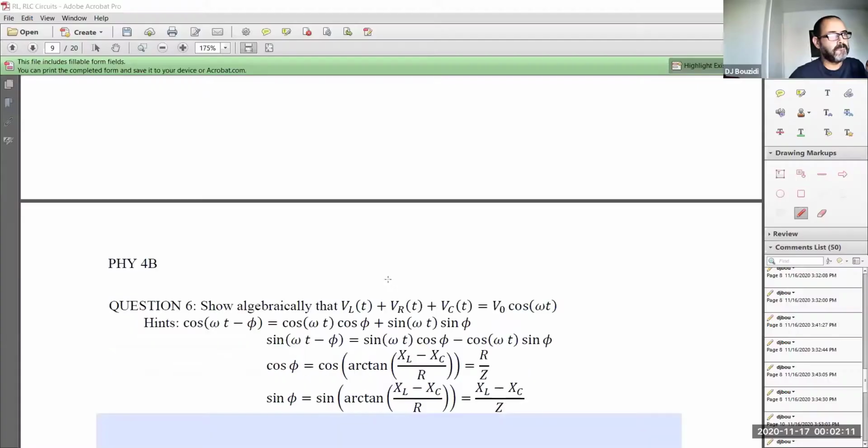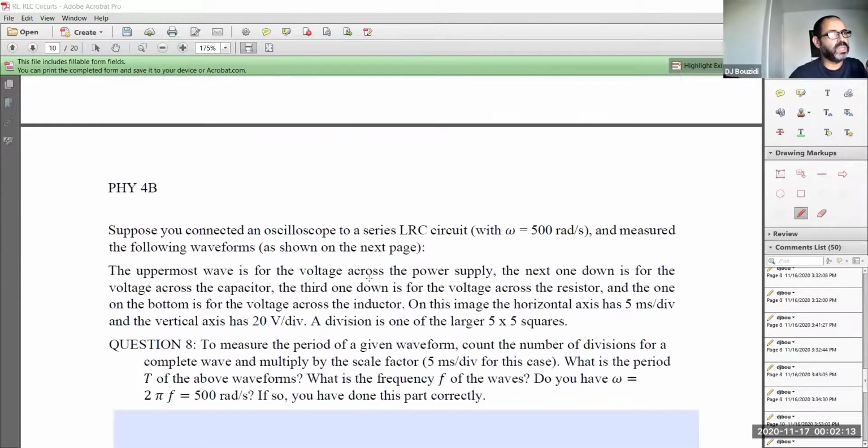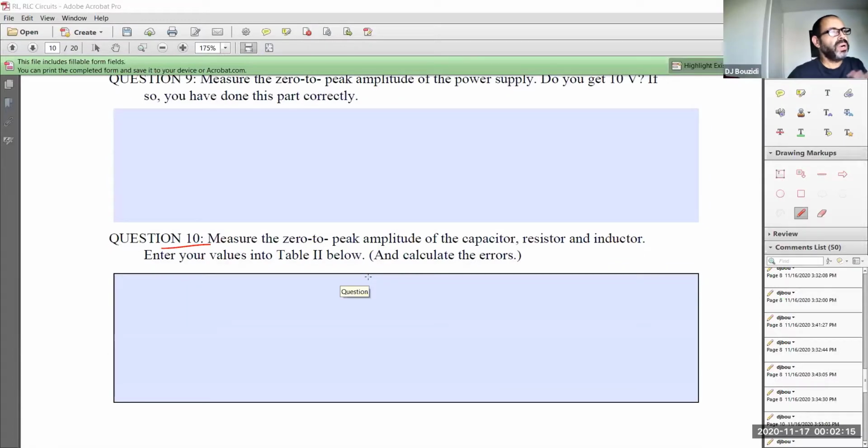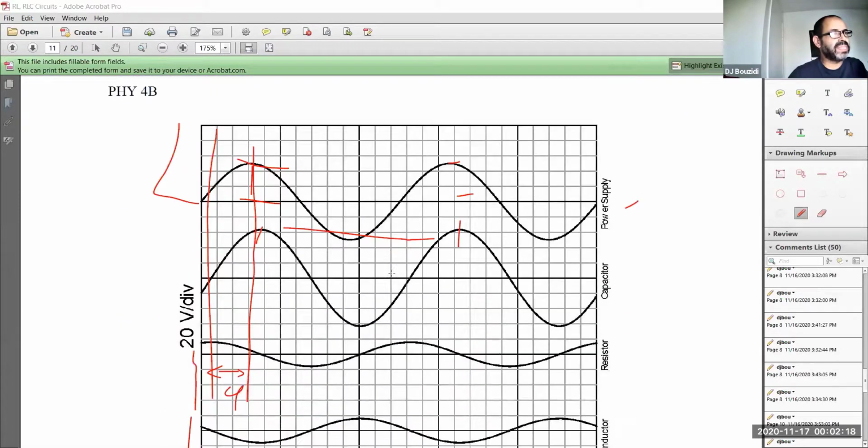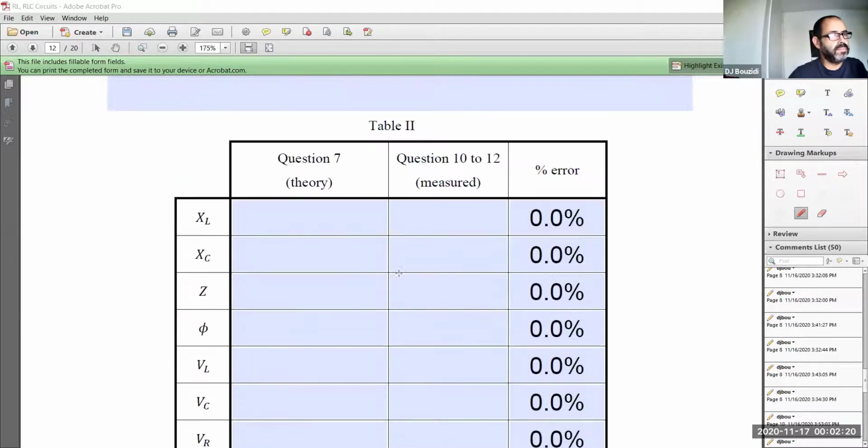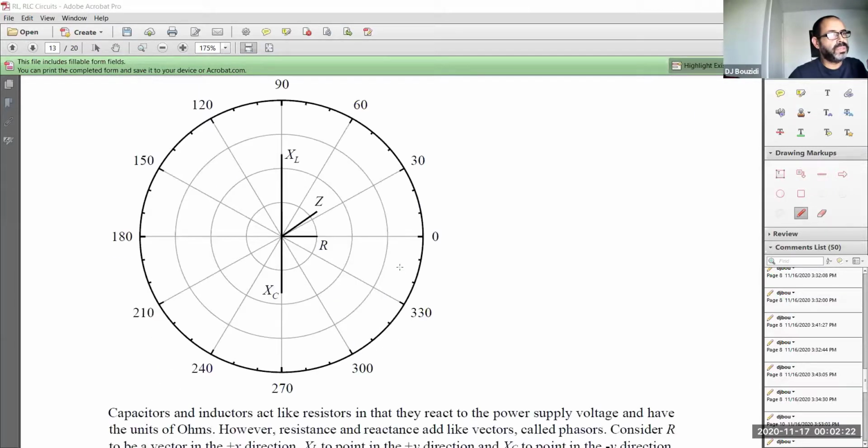We're going to draw this thing this way, using what are called phasors. So ignore the omega t minus phi and make them equal to 0. Since I have the voltage across the resistor, it is going to be along the x-axis. The voltage across the inductor is going to be ahead by 90 degrees. The voltage across the capacitor is going to lag by 90 degrees.